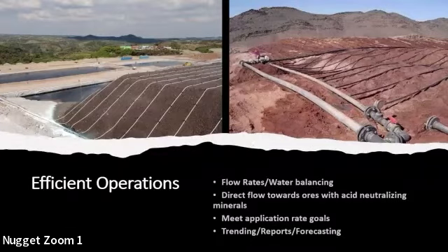The argillic ore exceeded the 100x safety factor anywhere from 40 to about 60 feet below the heap surface, and then the advanced argillic would likely fail at all potential lifts.